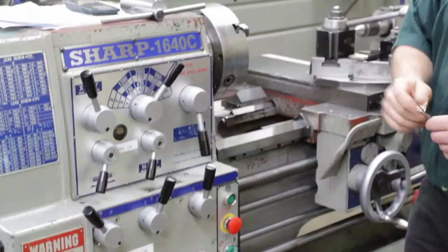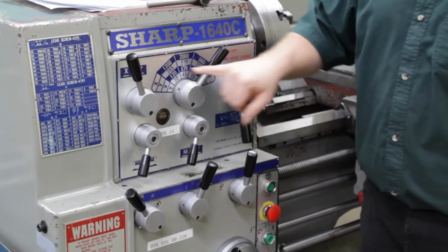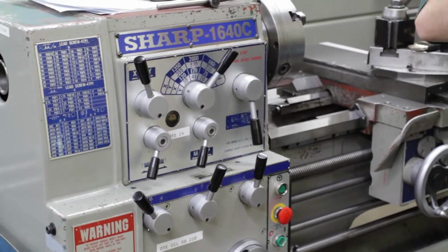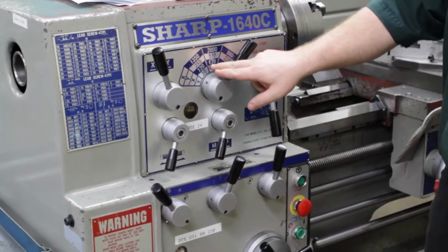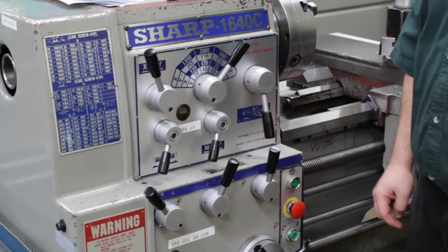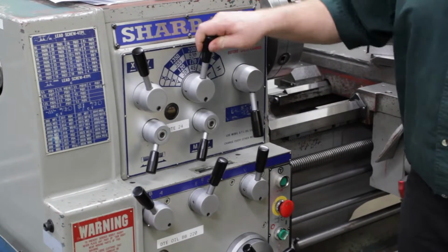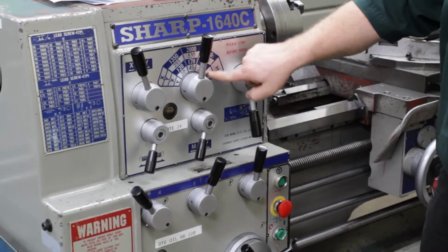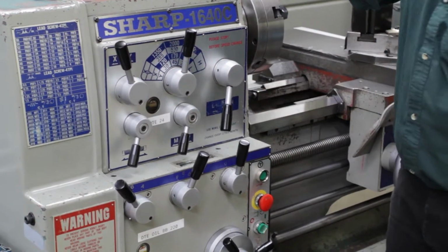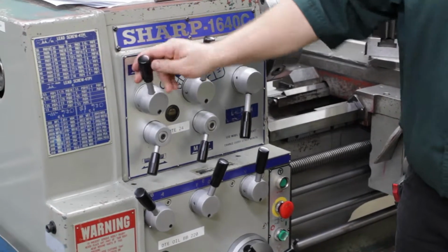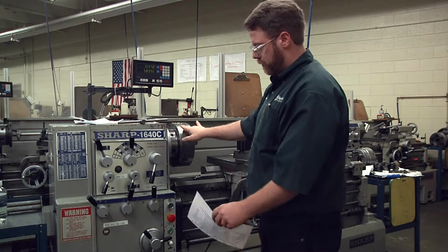On the lathe, you only really have 12 different speeds you can run. It ranges anywhere from 20 to 2,000 on this machine. So our calculator says that we need to run 182 RPM. The closest one I have is 170. So if I'm going to go 170, I have to put this handle in the middle position. That is in the low range, so I need to put this in low. And this has to be an X, which that handle already is. That'll set your RPM for this machine.